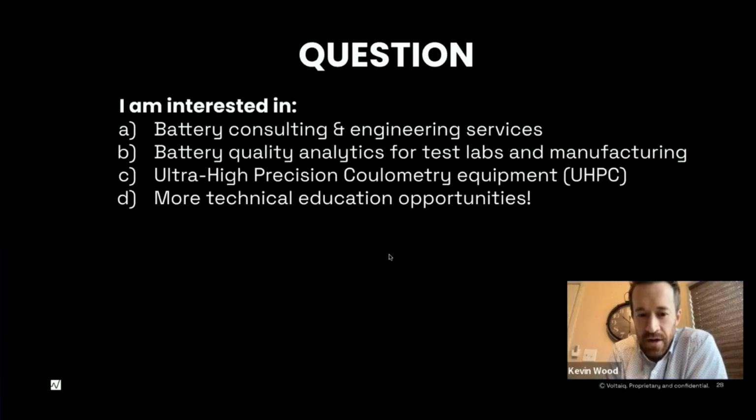All right, there's a couple more questions here. Yeah, how does peak intensity change with respect to cycle and DQDV? Normally it decreases over time, and Voltaiq has some automatic techniques for extracting information on peak intensities over many cycles. So you can plot it versus many cycles and see how that's actually changing. So normally it decreases. There are things where, like I mentioned, you can have structural collapse or phase changes as the cell ages or something like that. And you could see a shift, and all of a sudden one peak becomes less intense and another peak becomes more intense. And there's a lot of variation there.